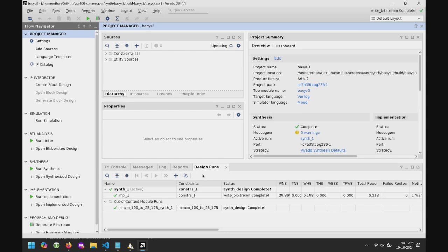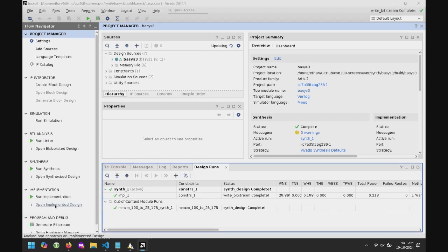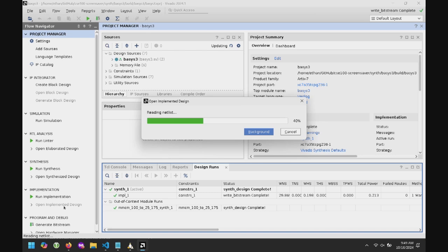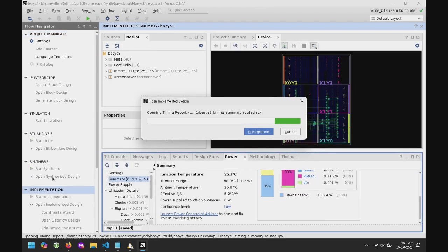Okay, good. So here is Vivado, and I wanted to open the implemented design. While this is pulling up, can someone give me a definition of synthesis again? You can also look back in your notes. What does synthesis mean in the Verilog flow? Exactly, yeah. So synthesis is when you take Verilog that you've written yourself, so high-level Verilog, and converts it into a netlist, which is just low-level Verilog, yeah.